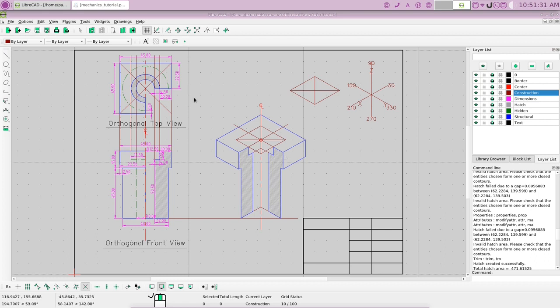Okay, so let's go to ellipse, because even though it's a circle, in an isometric view, it's going to look like an ellipse. Okay, so let's go to our structural layer. Let's choose an ellipse inscribed. Now, it says specify the first line. Well, that would be the line that we're inscribed in.